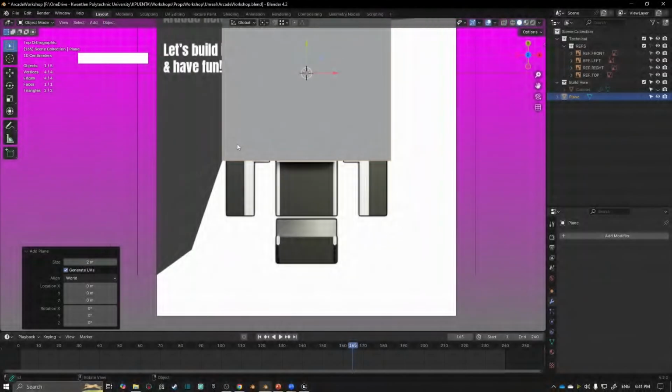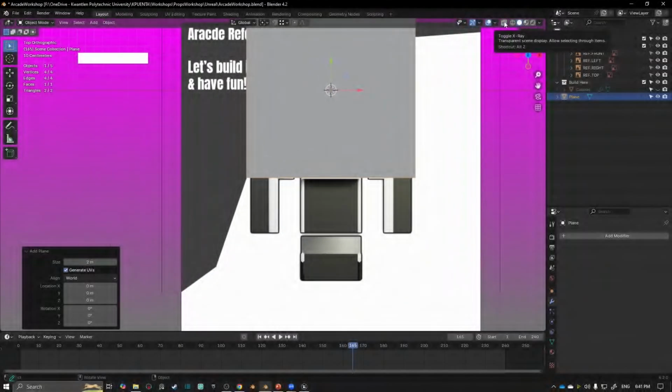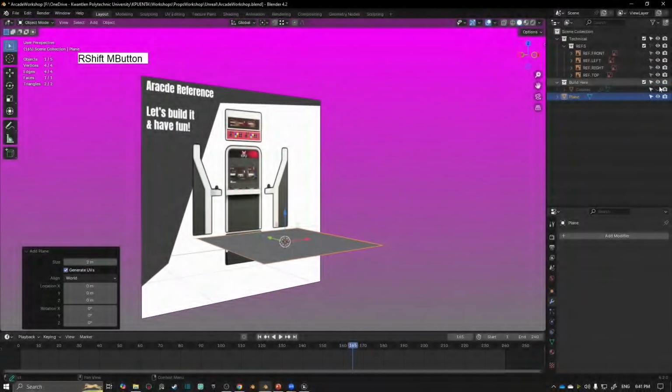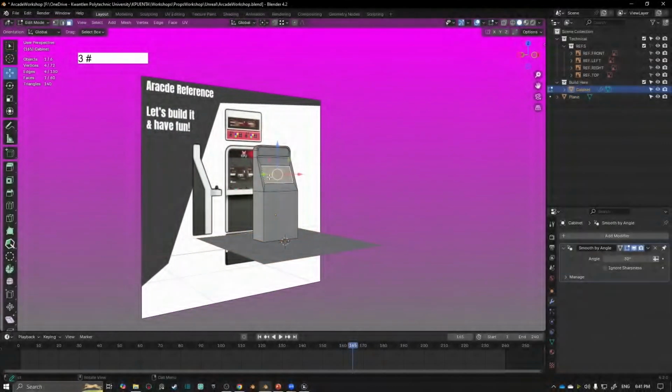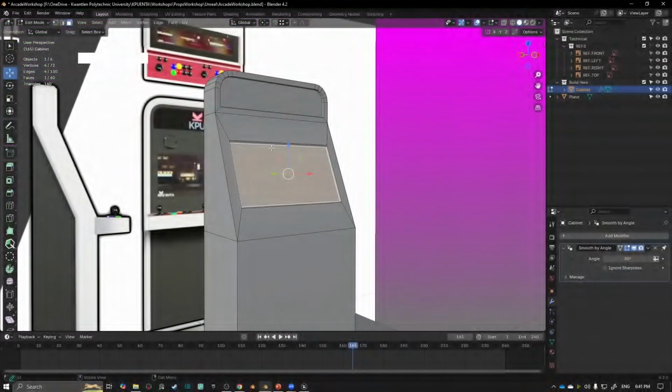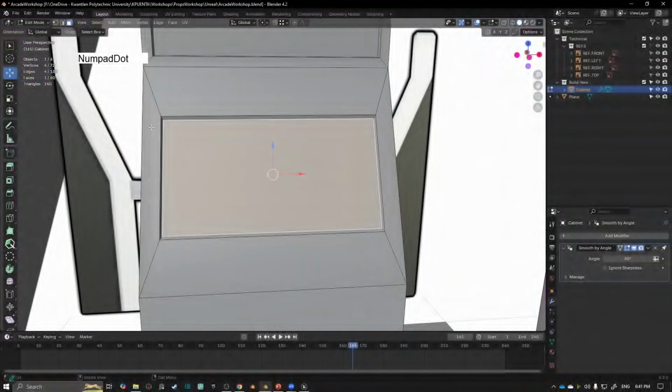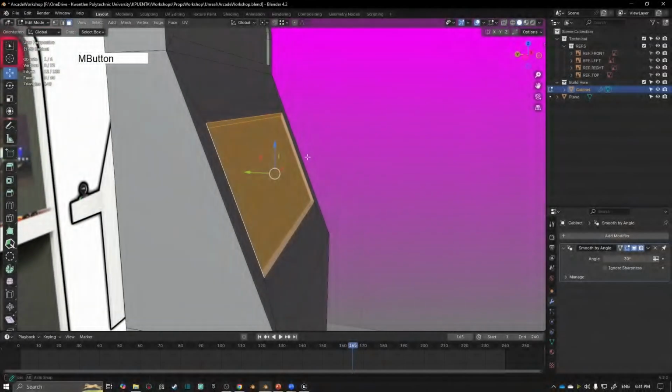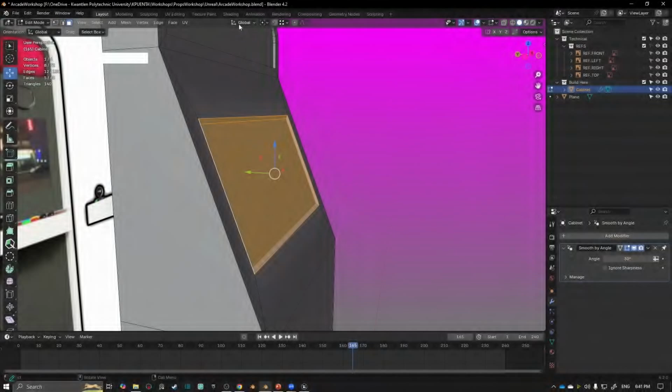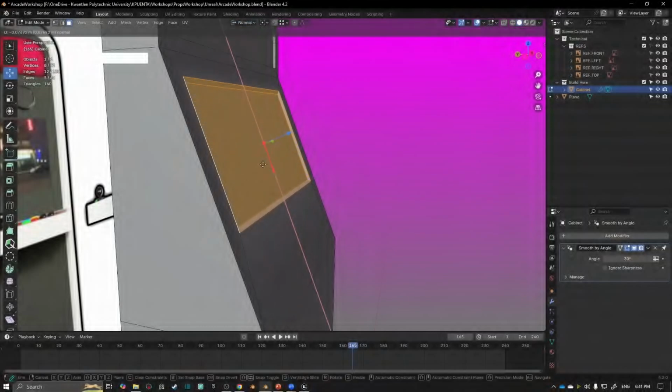Okay, so in my top view, I'll turn on, how can we move the intersect square on the steep face? Okay, hold on one sec. Okay, so let's say we wanted to move this whole thing, like this whole thing, but according to the surface. So what we could do is set the orientation to normals, all right, and then we could slide this along the surface normal.